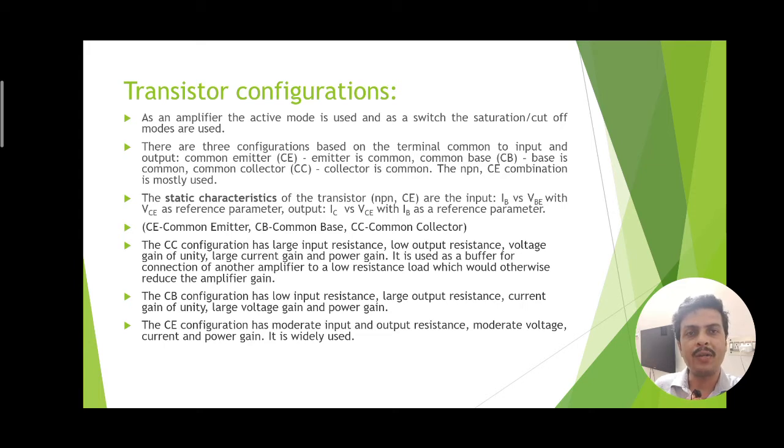It is used as a buffer or connection of another amplifier to a low resistance load, because common collector is having low output impedance. That is why low resistance load may be handled using common collector configuration.